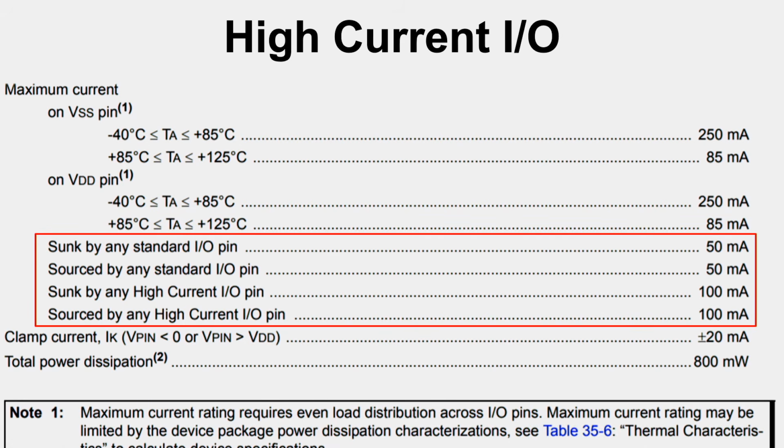In some instances, these are being touted as high current I/O. It's already 15, 20, 25 milliamps. But right now it's all in our standard I/Os, our new devices are all in our standard I/Os. But I want to make sure you keep in mind this is the absolute max value. Right. So in your real design, you probably don't want to reach that kind of level. Yeah, you run any device at its listed max current for too long, and you're bound to damage something. I usually run at like half of it. 50%, yeah. Okay.